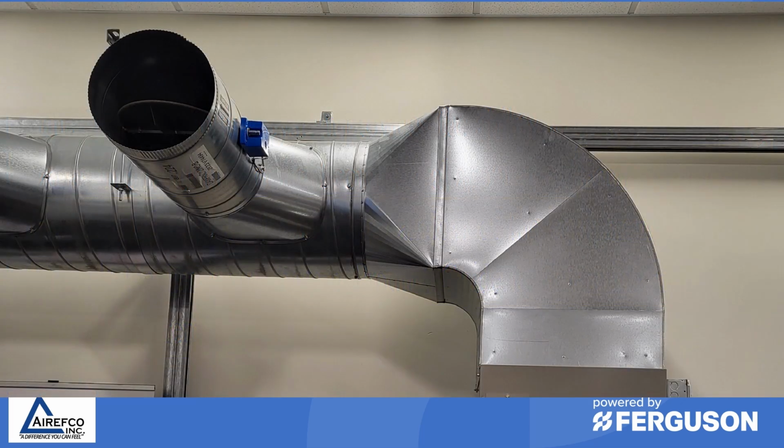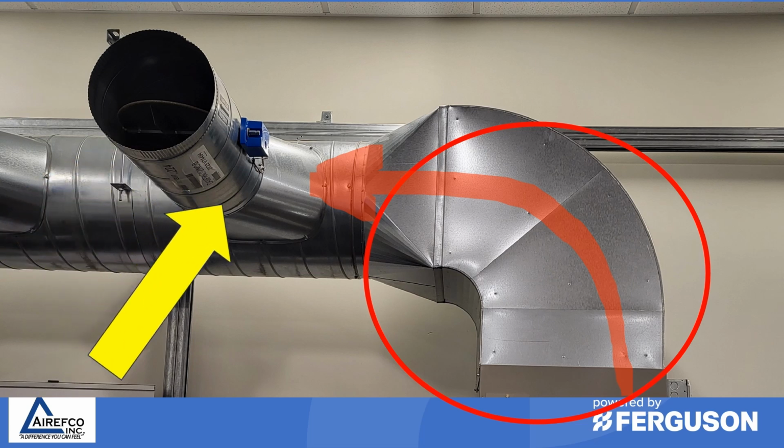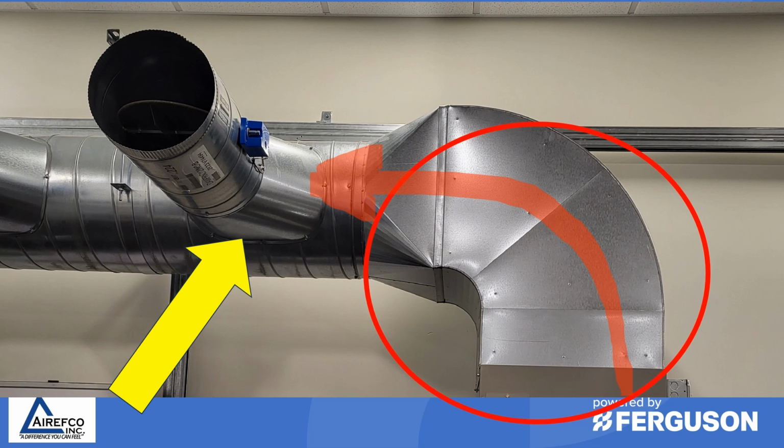We're not going to get into it in this video, but we have done numerous videos before of proper airflow throughout a system. On a zoning system, it is critical that you eliminate all turbulence and recirculation. By installing fittings like this, which direct the air, you reduce the amount of turbulence and recirculation that you may find on an HVAC system. Also note that on our takeoffs, we are using 45-degree angles to direct the air out to the zone. So make sure when you're designing your duct system for a zoning system that you take into consideration fittings such as these to provide the proper and smooth airflow to each zone.